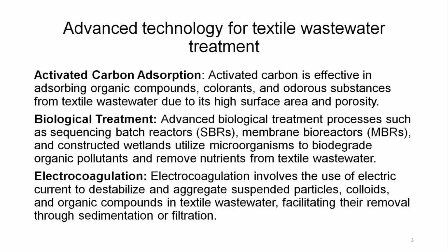Electrocoagulation. Electrocoagulation involves the use of electric current to destabilize and aggregate suspended particles, colloids and organic compounds in textile wastewater, facilitating their removal through sedimentation or filtration. And all of this we have studied in the past, but we will look at it in more details in this lecture.